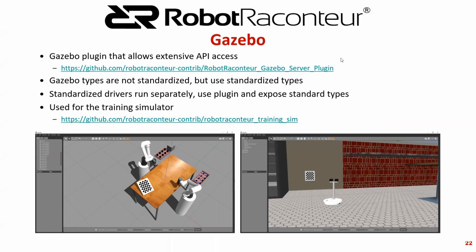So we also have a standard, well, the interface itself is not standard, but we use standard types for Gazebo. And that allows you extensive API access into Gazebo itself. And we have standardized drivers which talk to the plugin. They run as separate processes and they expose standard types. So we have the simulator, which is basically indistinguishable from real devices to the teach pendant and other clients. So we use this a lot for development. And I also recently added the iRobot Create as another scene in the simulator, which matches the tutorial. So you can run the examples now in Gazebo rather than needing a robot.